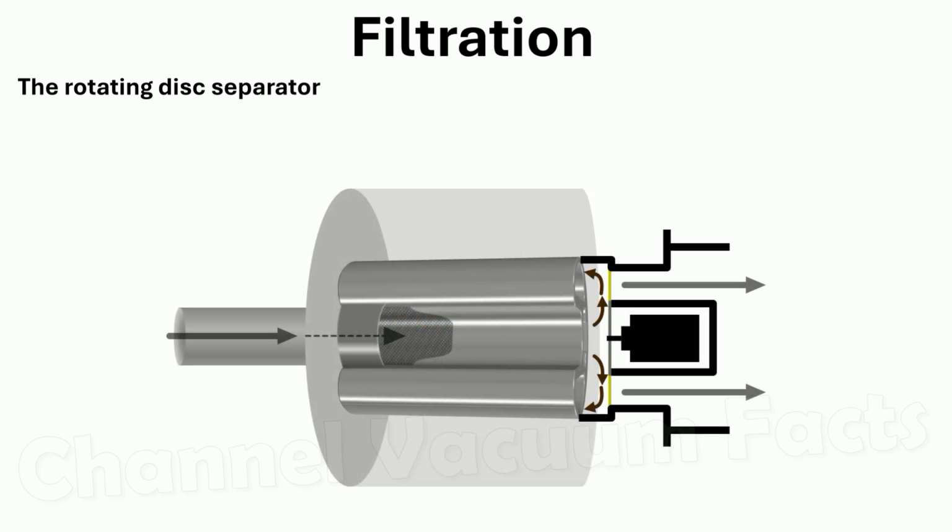It's quite possible that both the first stage non-cyclonic inertial separator and the rotating disc separator can be combined in the same design. Most of the dirt is removed initially at the first stage in the bin, and the work of removing the fine dust that would require cyclones can be replaced with a rotating disc. The ultrafine discharge from the disc can be routed just as the cyclonic discharge is currently.